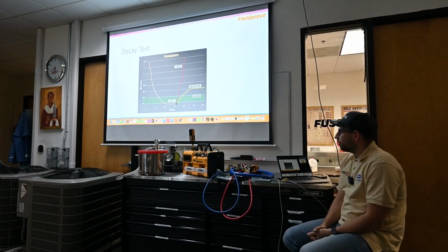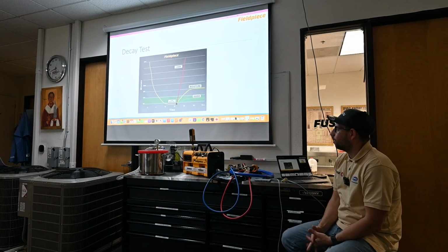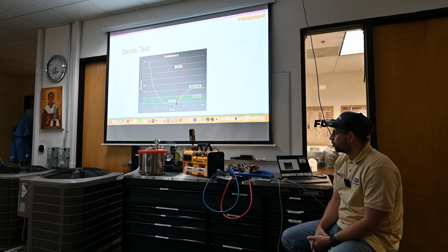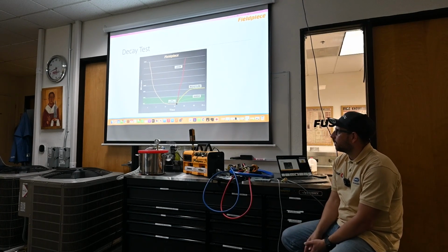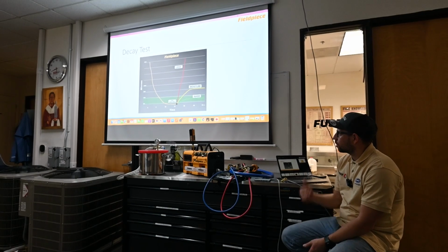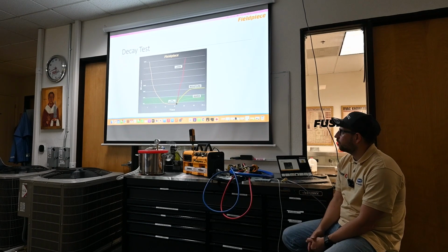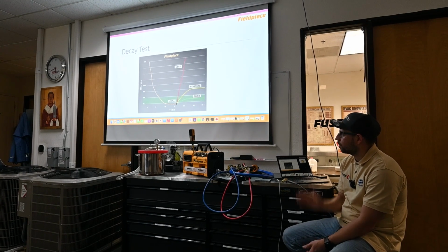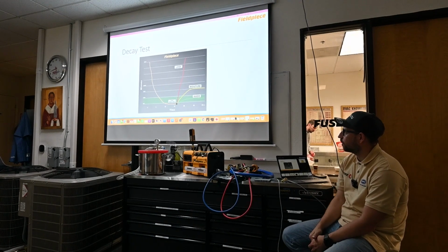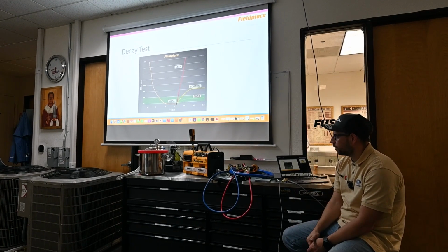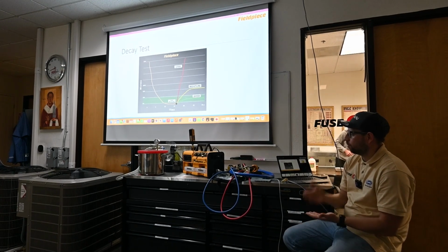Okay. If after minutes, when we shut off the vacuum pump, our microns stay between 500 to 1000, it's good. If microns go up to 5000, it means there is moisture. And if microns go up to more than 10, 15, 25,000, it means we still have a leak. We need to figure out exactly where the leak is, fix the leak, and turn the machine back on.